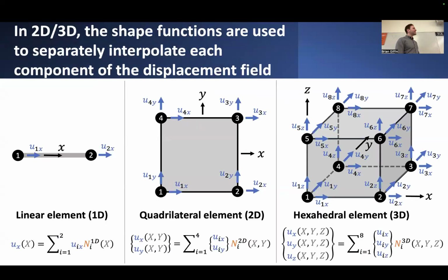Well, in the case of 1 dimension, it was fairly straightforward. We can come up with these linearly interpolating basis functions that interpolate these 2 distinct values of the nodes. Over a quadrilateral domain, I might have these 4 nodes that I need to interpolate. And in the case of a 3-dimensional domain, this cube, now I have 8. So things become a little bit more difficult to swallow.